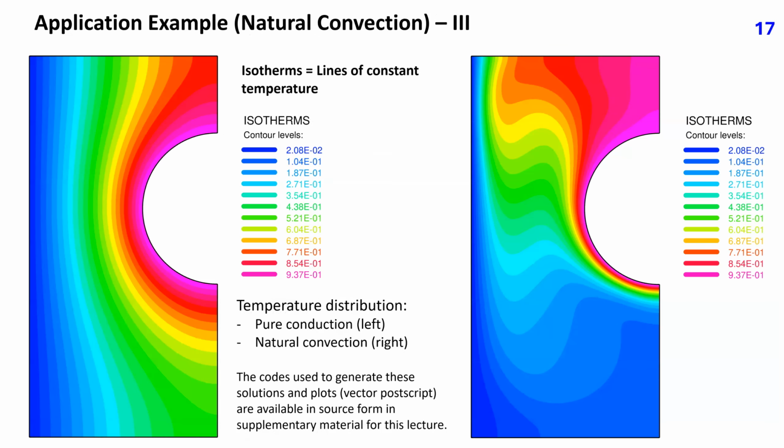In simple geometries, one can derive a simple expression for the Nusselt number, which is the ratio of heat transfer due to convection and conduction normalized by the heat transfer by conduction alone. For this geometry and boundary conditions, such a simple formula does not exist. For this reason, pure conduction is considered first by solving only the energy equation. This would not be possible to do experimentally because as soon as temperature differences are present in fluid, it is set to motion due to resulting density differences and gravity. In a numerical simulation, there is no problem in solving the energy equation alone.